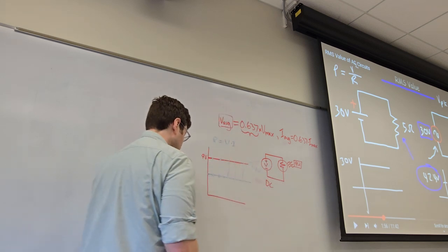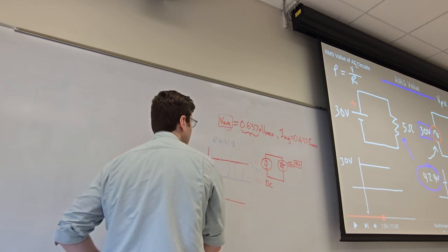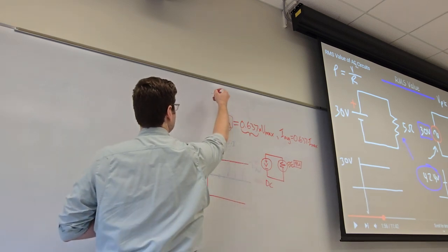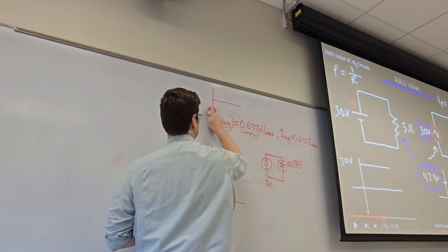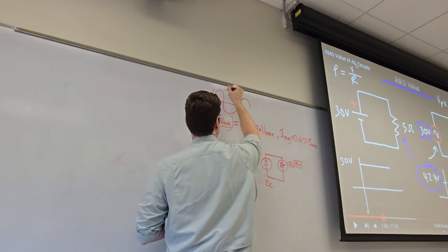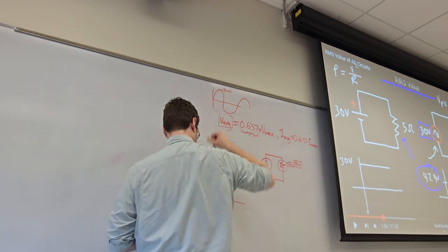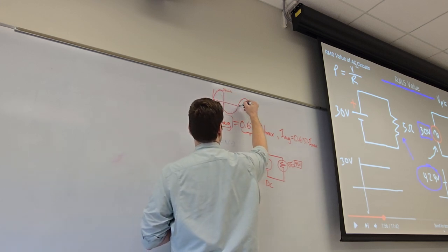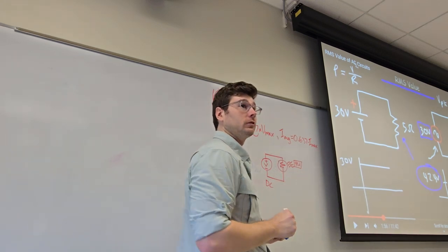But AC doesn't work like this. So we're trying to figure out, in the AC waveform now, here is our 0 point. Sorry, I should be drawing this crosswise. So now our signal goes like this. We want to figure out how high this V peak needs to be in order to give the same amount of energy delivered to our resistor, so it'll heat up the same amount. So it'll heat up 9 watts worth.